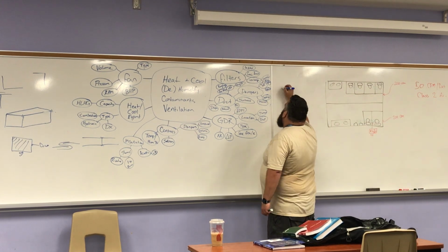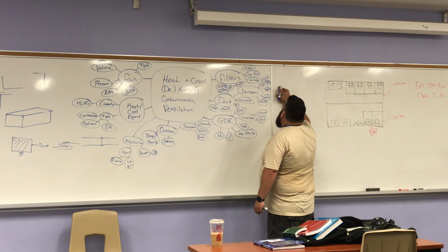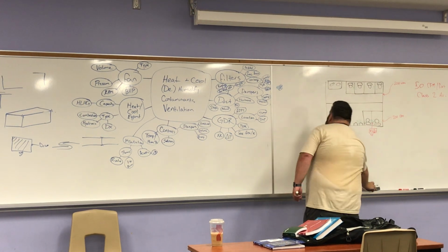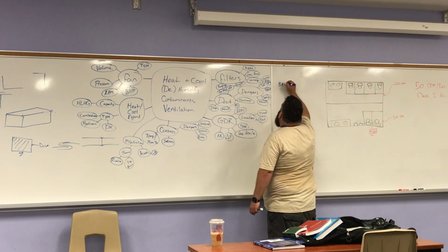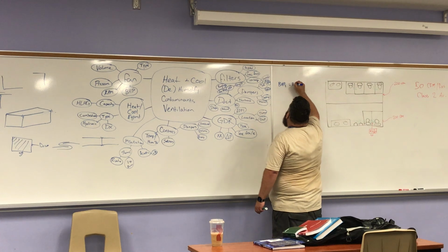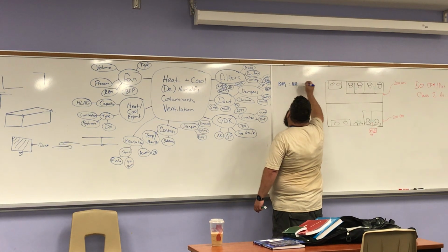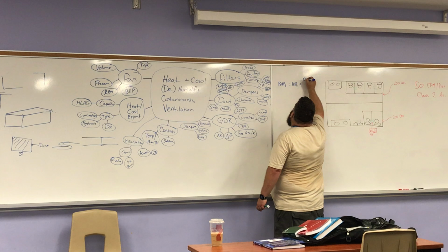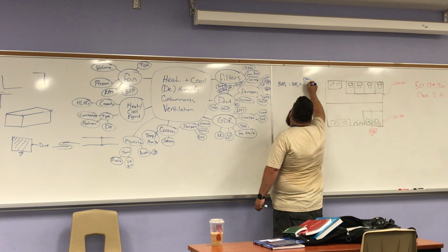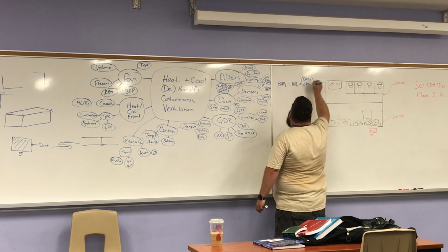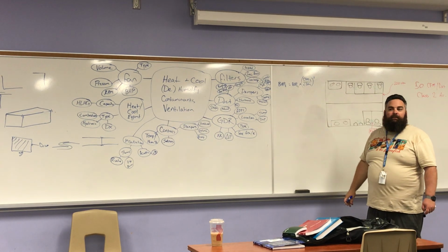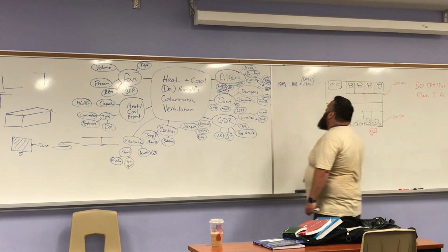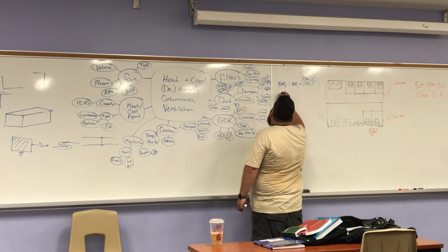So brake horsepower 2 equals brake horsepower 1 times CFM 2 divided by CFM 1, cubed. By the way, which fan law is this? Is it 3? It's the 3rd fan law. Excellent. So BHP2 is a question mark.